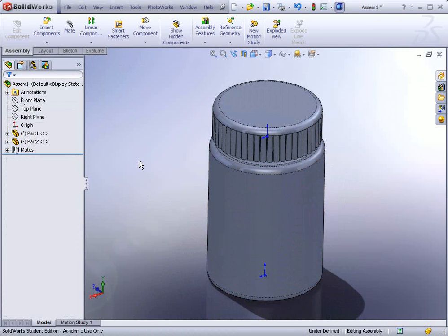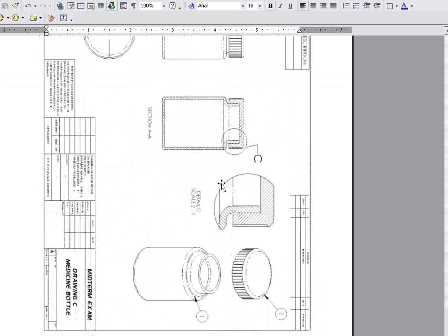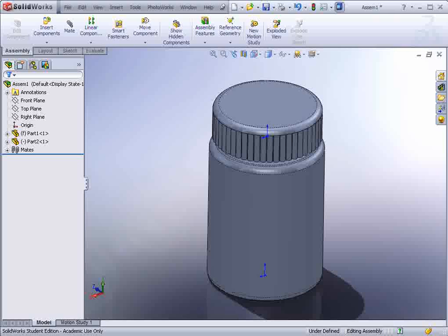Now let's move on to the fourth section. Before we do, in the drawing, it actually shows an exploded view, and it's in isometric mode. Exploded views work this way. You cannot actually explode it inside the drawing. You have to explode it in the assembly file first to have it show in the drawing. So this is what we do.